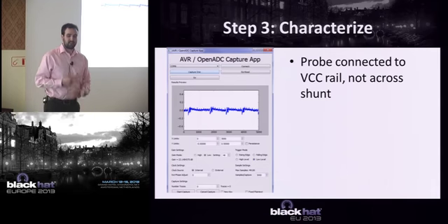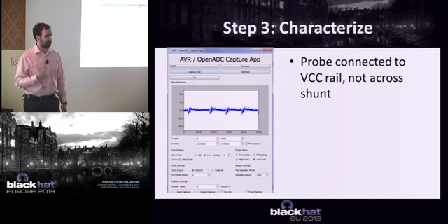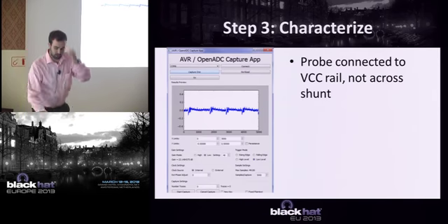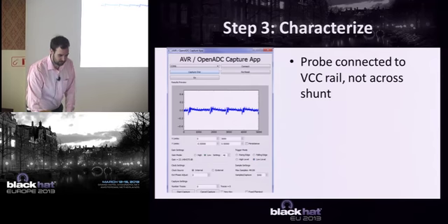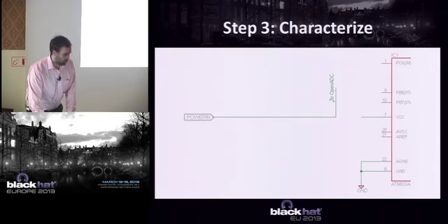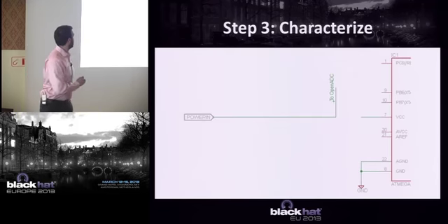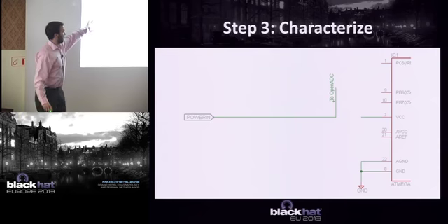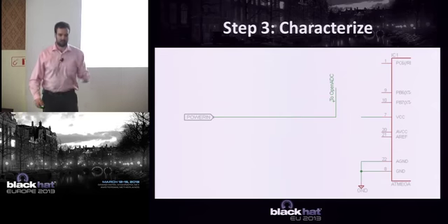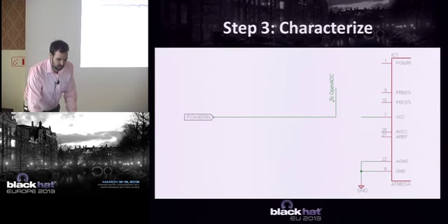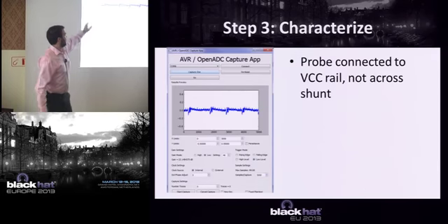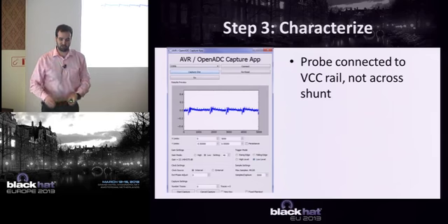Once you start looking into this, you'll have to ask how noisy is it, how well is this going to work. So one of the first characterizations I do, or you should do with these boards, is I've connected the probe just to the power inline from the voltage regulator, or the voltage supply I'm using. What you don't want to see is this. You don't want to see a bunch of noise on it because that's going to give you trouble.